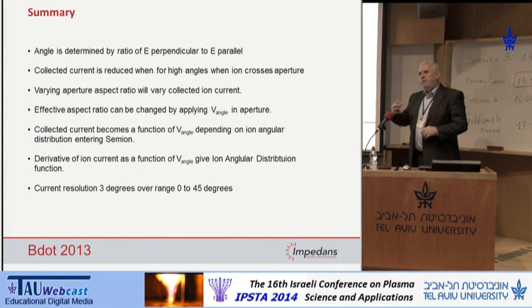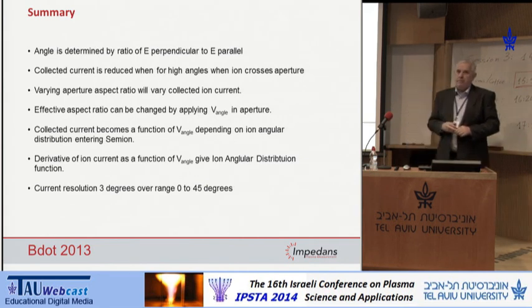So we find in low energy applications where you're up to 100 eV or 200 eV, you can get away without suppressing those electrons. It adds about 20 to 30% to the current and depends on the gas. But at high energies, 500 eV to several thousand eV, the secondary electron emission can exceed the ion current, and so you have to use a 4th grid to suppress secondary electrons. Okay, thank you again.